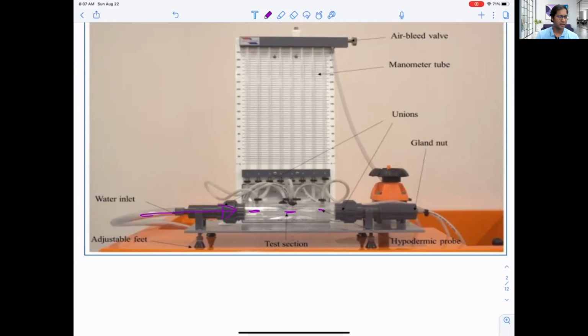And there are many other practical applications, and we'll see them from time to time in this experiment. Also, in order to design any cross section of a river, if you want to see what will happen, we'll apply the Bernoulli equation at every section of a river, a channel, or a pipe. In order to design a pipe network, we need to know the head loss, and how can we calculate that head loss? There's another equation as well to calculate the head loss for a pipe or pipe network, called the Darcy-Weisbach equation. That's another story, but for the time being, we'll apply this energy equation, that is called Bernoulli's equation.